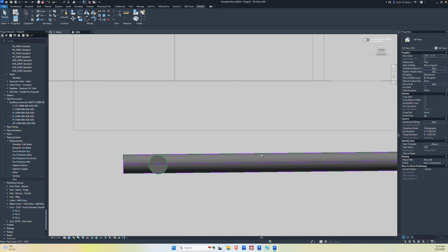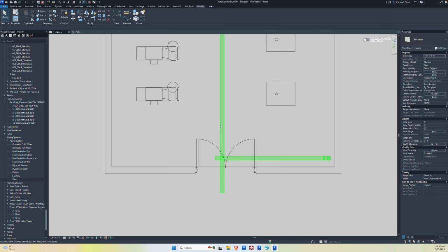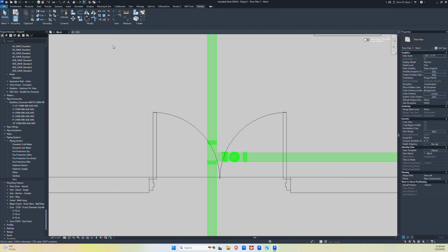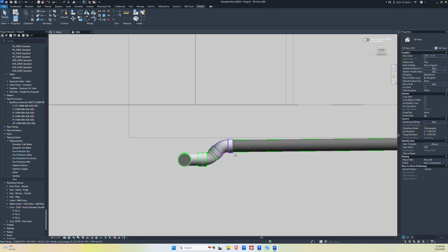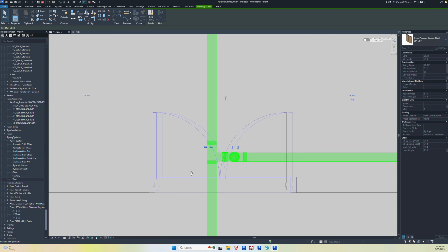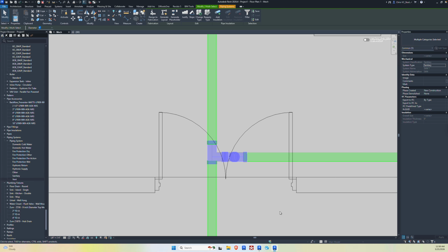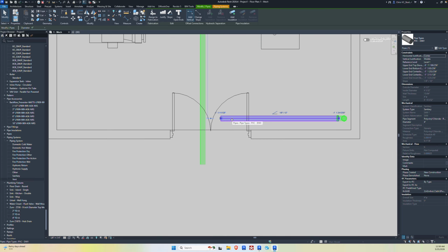Let's go back to the 3D view and drag this up. Now you can see it's clearly up high. If I try to connect it, you're going to see some ninja stuff start to happen. It's going to try to come off the side, throw in a couple of 45s, and make everything work to connect. That's nothing that we really want to do. So let's delete this, trim these back together using the keyboard shortcut for trim, and now we'll shorten this up.